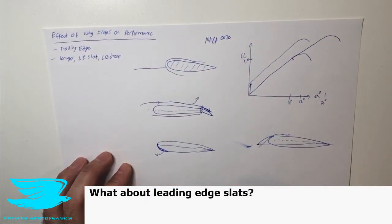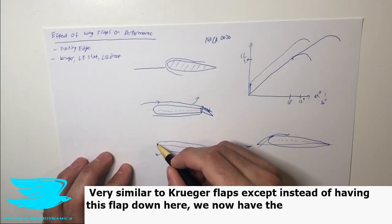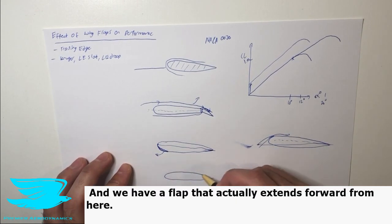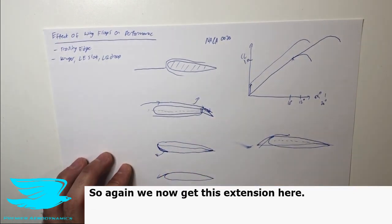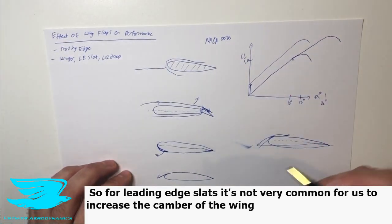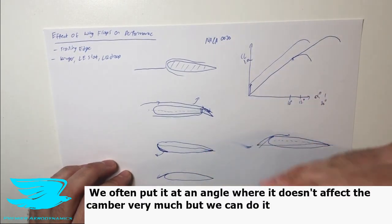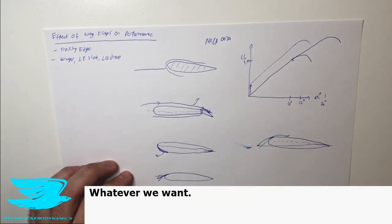What about leading edge slats? Very similar to Kruger flaps, except instead of having this flap down here, we now have the airfoil, and we have a flap that actually extends forward from here. So again, we now get this extension here. For leading edge slats, it's not very common for us to increase the camber of the wing by extending this. We often put it at an angle where it doesn't really affect the camber very much, but we can do it if we want to. We can extend it further down this way more aggressively or less aggressively, whatever we want.